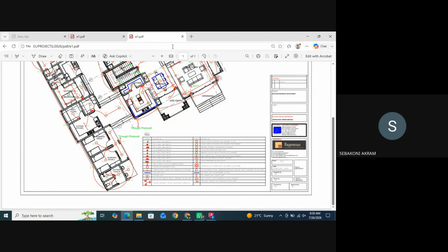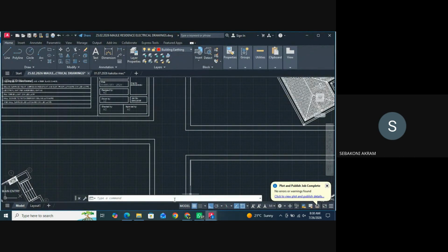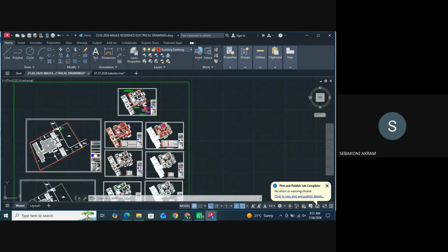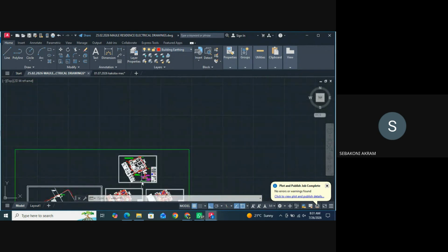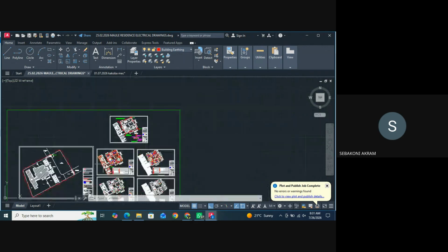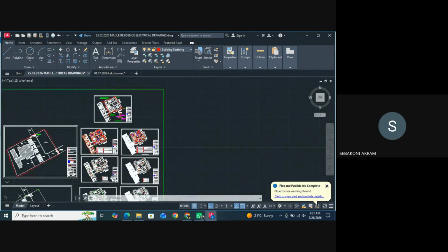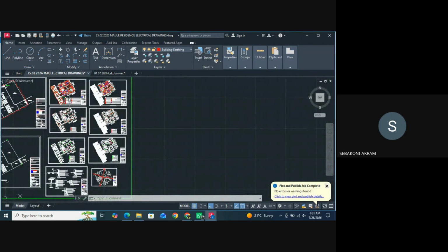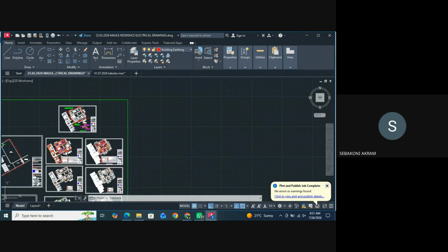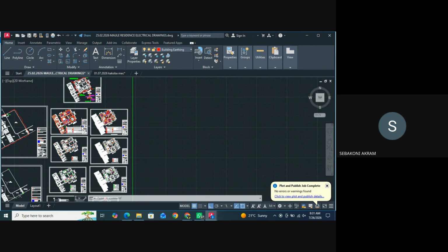As your E1. Then after you print all those pages one by one, do you have Adobe on your PC, Martin? Yes. So you know how to combine PDFs. Then you go to Adobe, combine those PDFs, you form one PDF. You print them in order. Earthing usually is your one, then lighting ground floor, then small power ground floor, then low current ground floor. So you first finish all the ground floor. That's how you even label them.